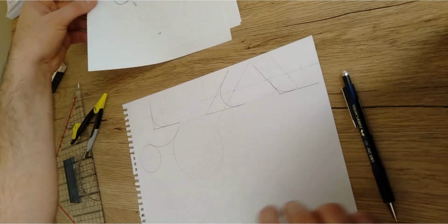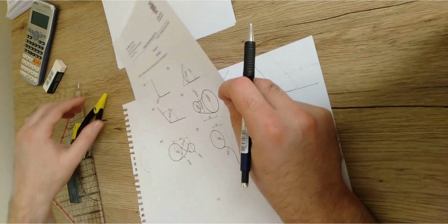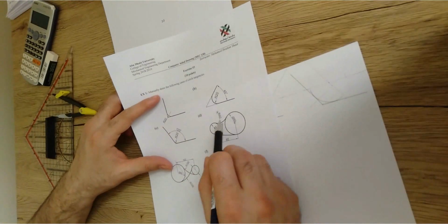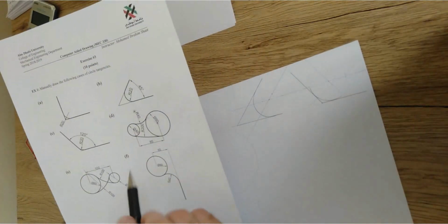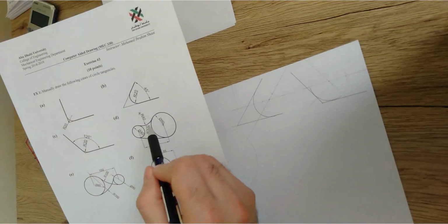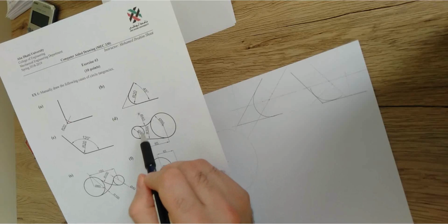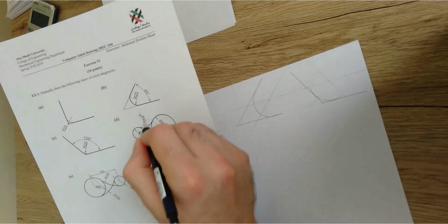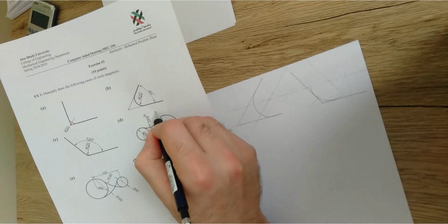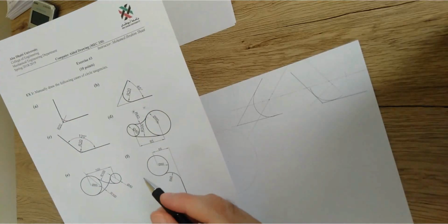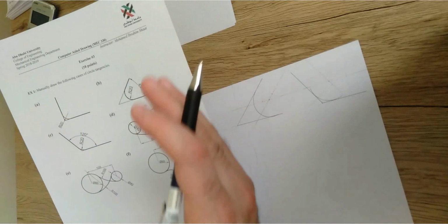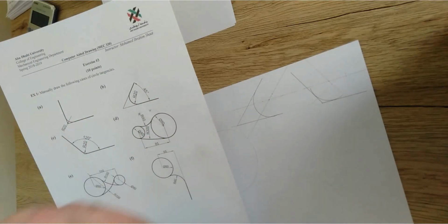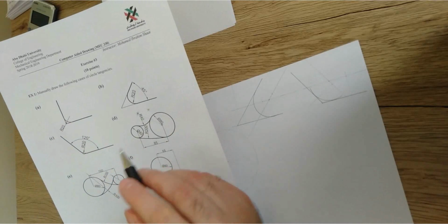So for the 300, it's gonna be very similar. You're just gonna ask yourself the same questions. Where is here? We are working over the 300 radius, right? So if I ask you where it should be the center of the R300 radius of this curve, it should be above, on the top, above here, at this point. So this is the first question, or the first step, just virtually locate the center of this curve.